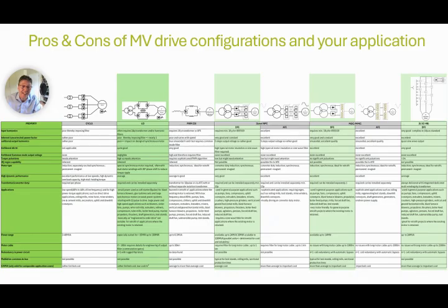The power range for each topology varies with the drive manufacturer. The load commutated current source inverter LCI is particularly suitable for drives starting from 15 MW. The LCI can increase the drive's output voltage by adding thyristors in series, thereby increasing the available output power.